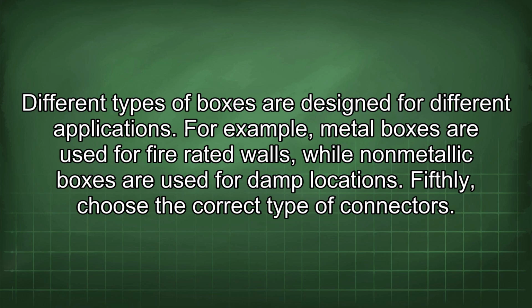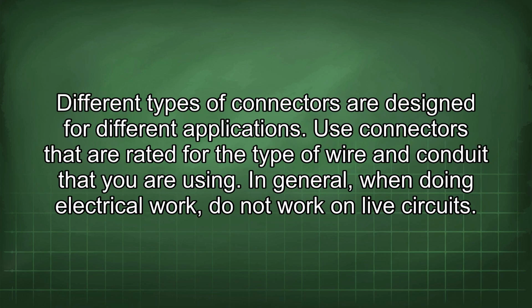Fifthly, choose the correct type of connectors. Different types of connectors are designed for different applications. Use connectors that are rated for the type of wire and conduit that you are using.